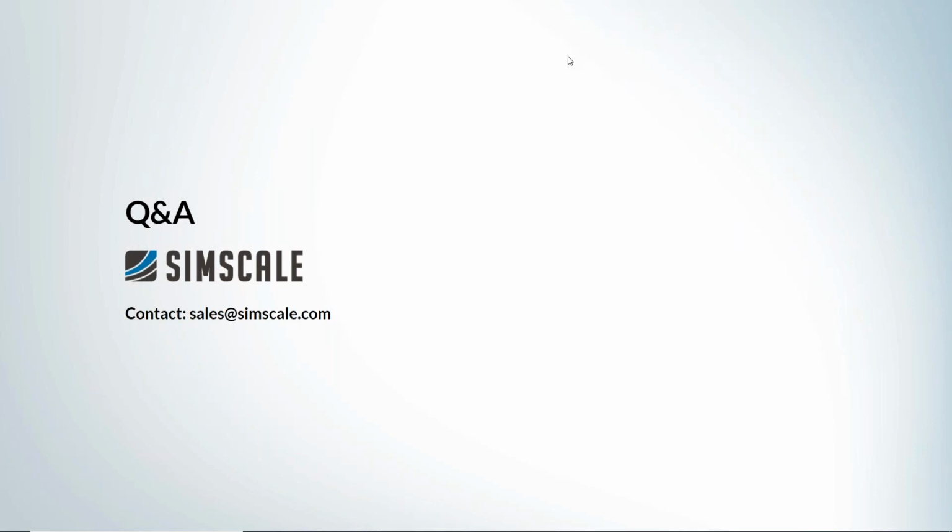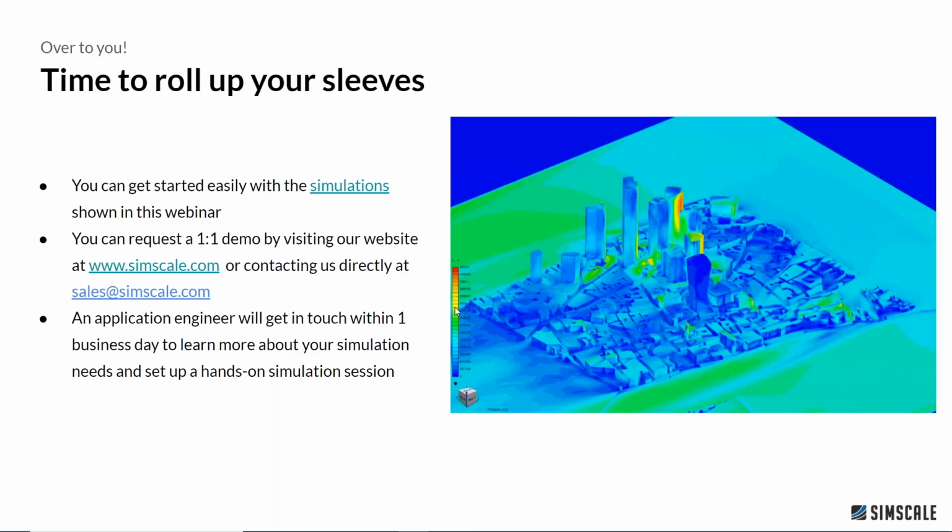In terms of other results, for each wind direction, you will get a full set of CFD results. You will get your wind speed both in steady state and transient. You'll also get your turbulence quantities and your pressure values. So if you are less interested in pedestrian comfort and more interested in facade pressure, you could also get that out of the same simulation.